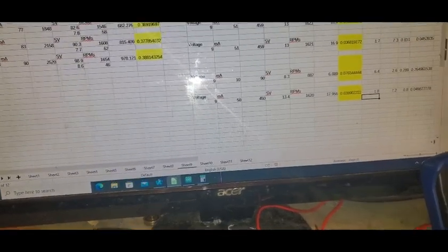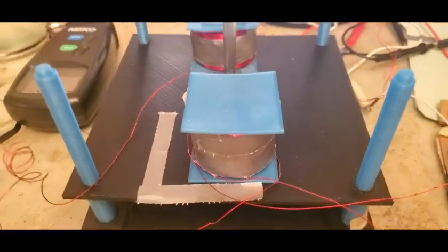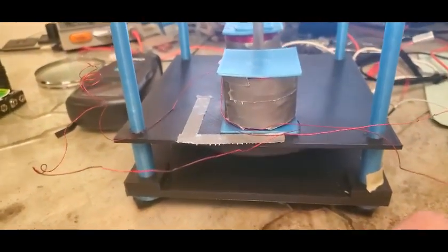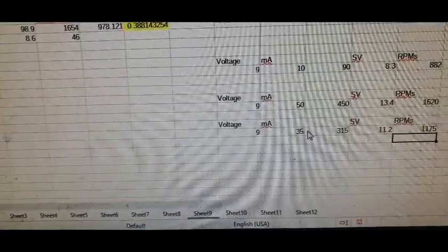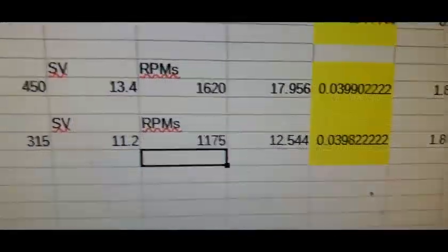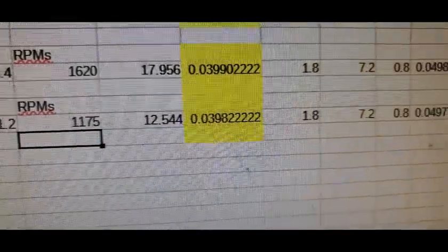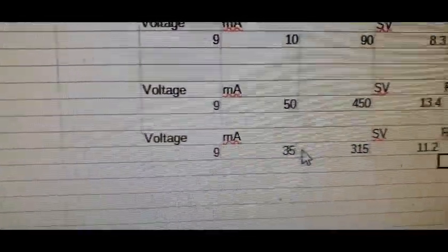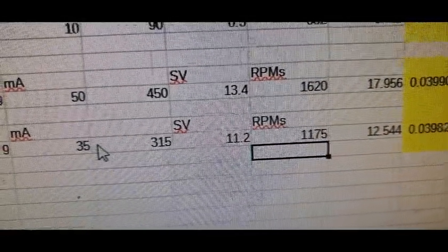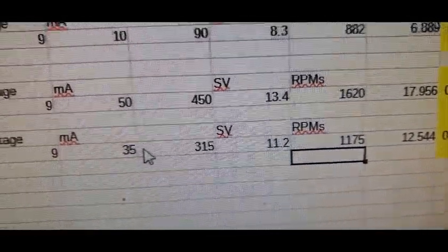So, all right, let me just throw that in the spreadsheet. Oof. Huh. So this one makes 0 sense. Every single thing seems wrong. One, there doesn't seem to be back EMF showing up here, and there was no more back EMF, even though you added a second coil. Where is it? 1.8, 1.8, not 7.2. 1.8, 1.8. Yet, in that case, the rotor shouldn't have slowed down, yet it slowed down dramatically. It slowed down about as much as the other one.